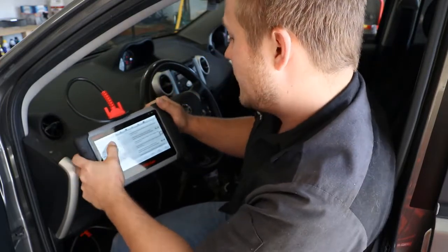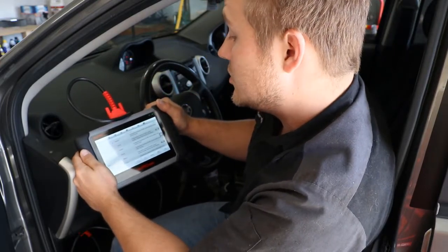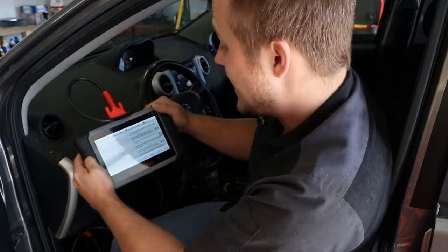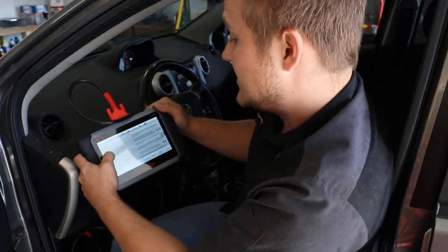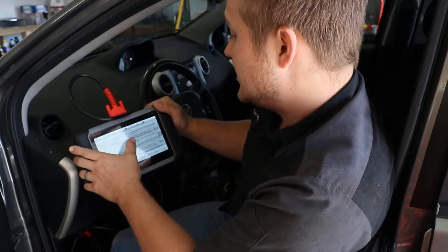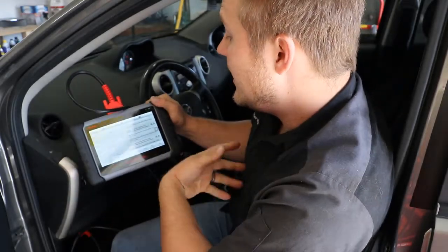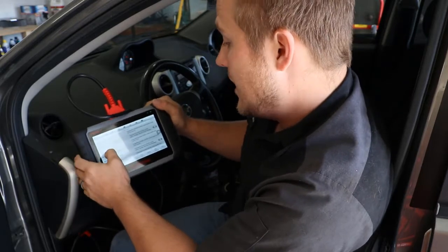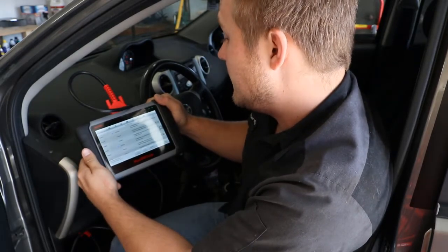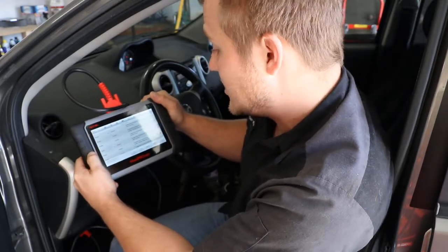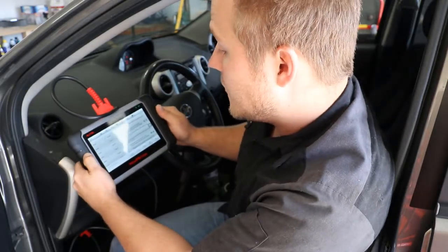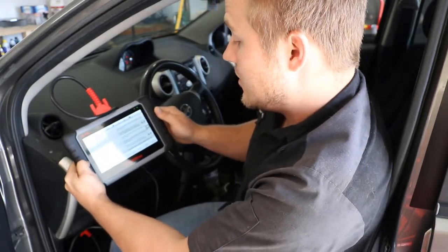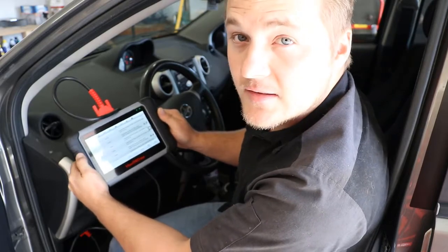It says here on the right, 441 is an evaporation control system purge flow incorrect, which could be our purge valve in the engine bay, which I'll show you where that is and how we're going to test it. Evap control system leak detected. It says a small leak. Again, the purge valve, if it is sticking open or not opening, or there's a leak in the system somewhere, will cause that. And then it says the evaporative control system vent control circuit. That's going to be back on the canister, which should be on the back side of the car. So we have 3 codes, 441, 442, and 446. Let's go ahead and start to look at some of those troubleshooting codes.